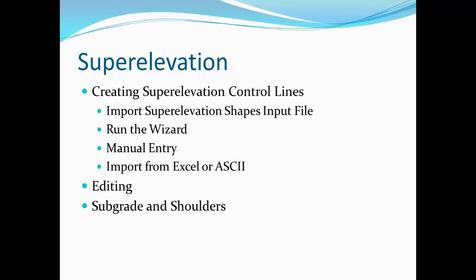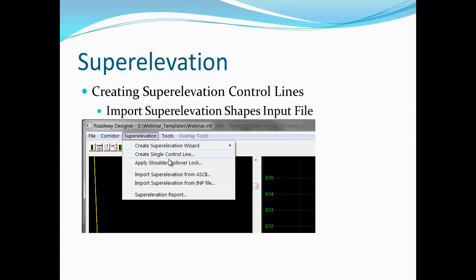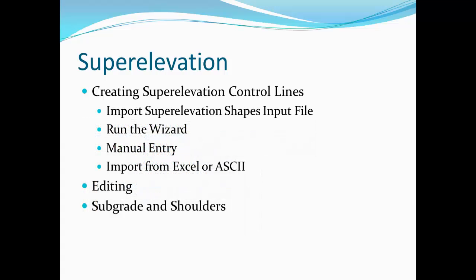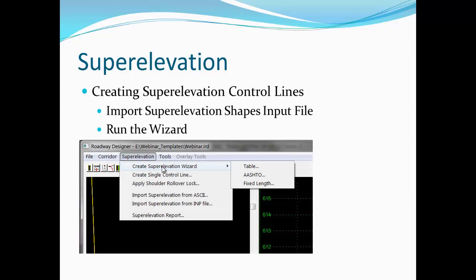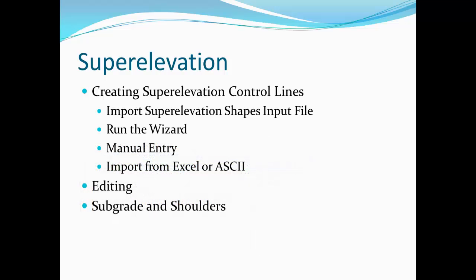Superelevation. Within Roadway Designer, there are a number of different ways to get the base superelevation data into the program. You can still use the superelevation shapes and import the input file into Roadway Designer if you still prefer that route. Roadway Designer does have several built-in options that run a wizard to add superelevation.